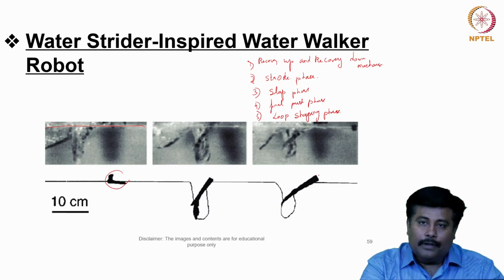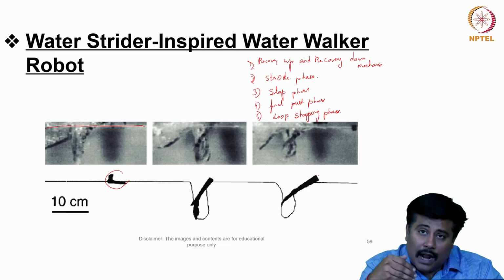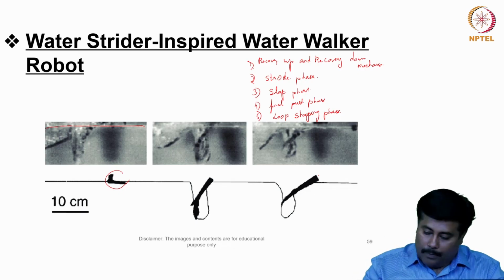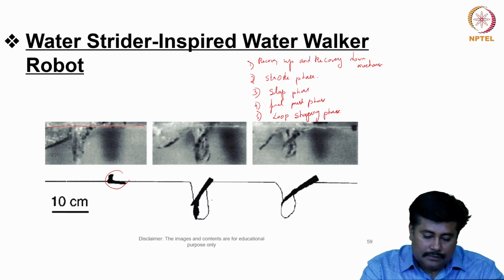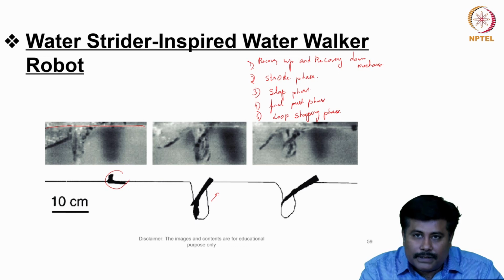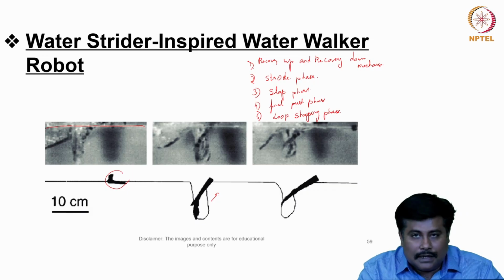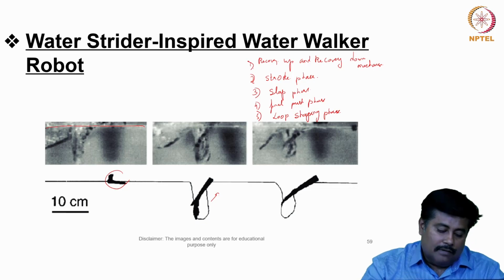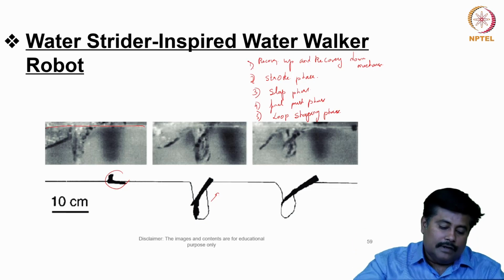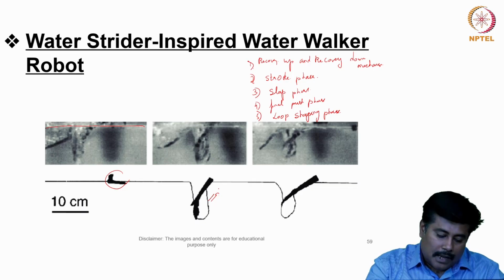As far as the slapping phase is concerned, during the basilisk slip, the slap phase can convey an extra amount of lift depending upon the speed, the contact and the power abilities of the lizard. This phase of the step is for all positions where the ankle height is lower than the water height and the velocity angle is less than negative 45 degrees. At this time, the slap phase is covered, in the hope that it will yield a conservative estimate on the lift provided by the robot, as the slap phase in reality provides a surplus amount of lift.